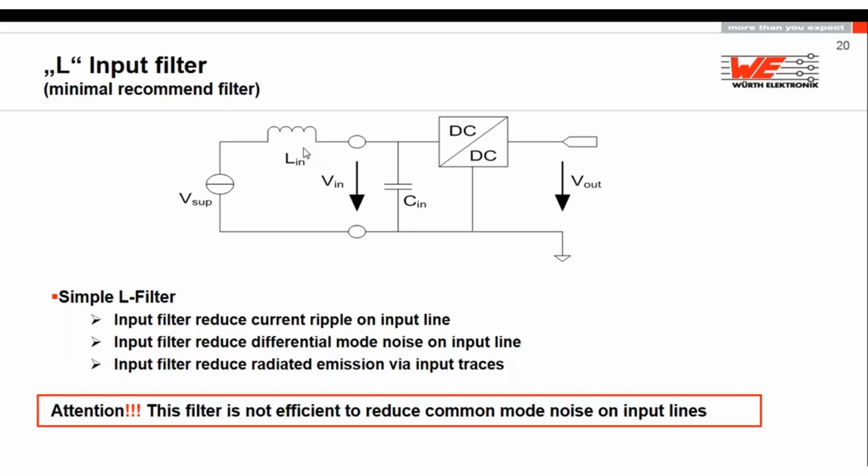If you think about this inductance value, you can try, like I told you, between 2.5 microhenry and 47. But a good starting point: I always start with 10 microhenry, and then I see, okay, I need a little bit more filtering, then I go up to 22. Or if I have a high frequency issue, maybe the resonant point is already reached, so I go down to 4.7 and try in this way.